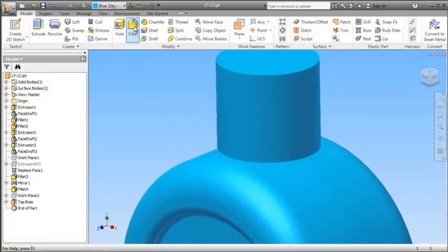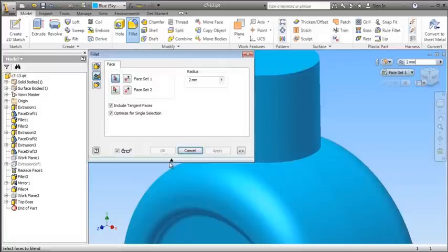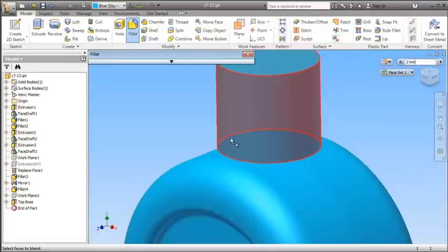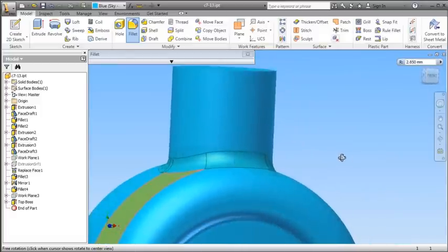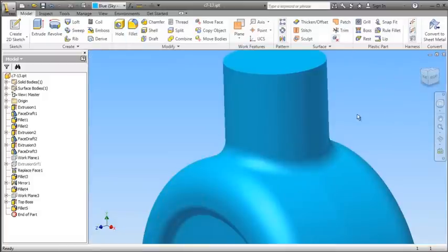This is another option one of our fillet tools can solve by using the face fillet. The face fillet allows me to select any two sets of faces, and it will simply fill that geometry in with a fillet feature. It will even offer me a suggested radius that will work. I can refine that if I like, and it will update the preview. When I'm satisfied, I place it, and it goes ahead and generates the fillet.